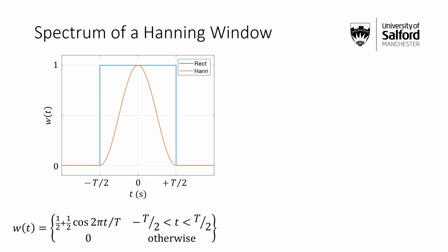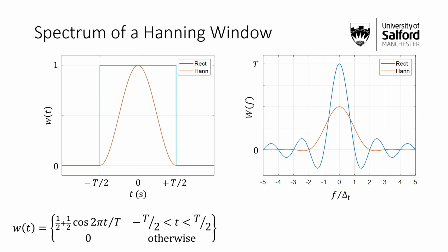And if we look at the spectrum of that, which is the smearing function, we've seen what's important. We can see that we get a wider though lower main lobe, but then very quickly get to 0 at the sides. So you can actually look at the main values here. The sinc function has a value at T, as we know. We've got a value at T over 2 and two values at T over 4 at the neighbouring frequencies.